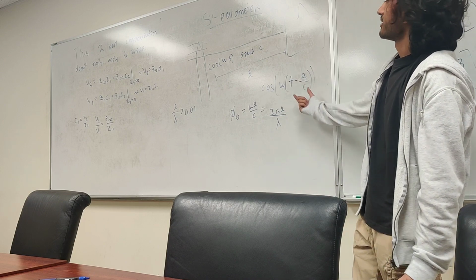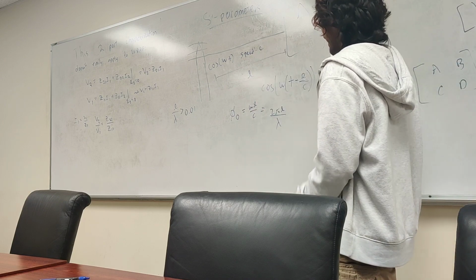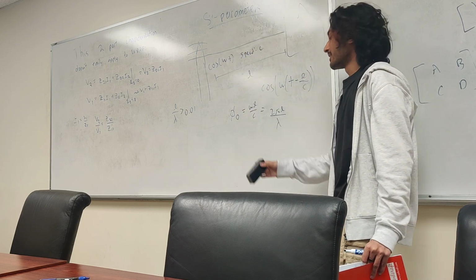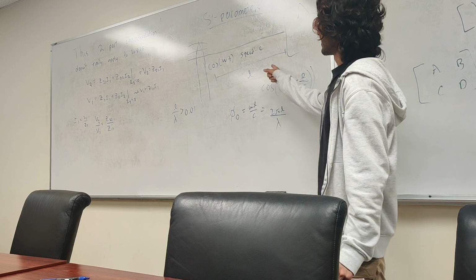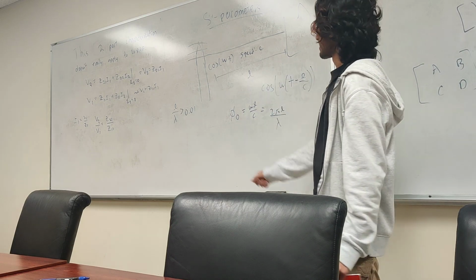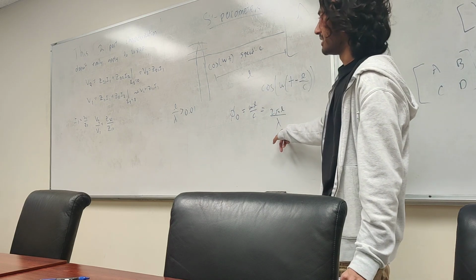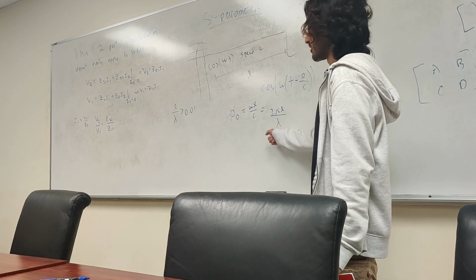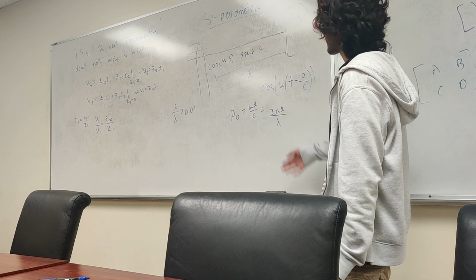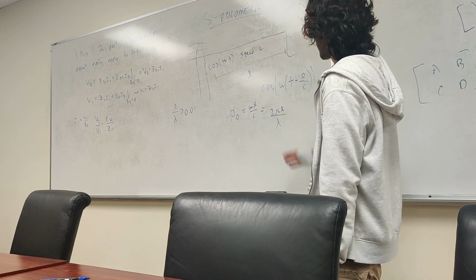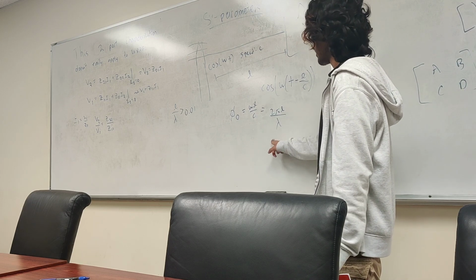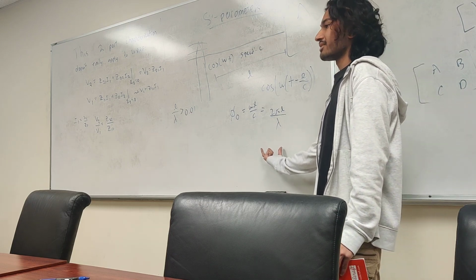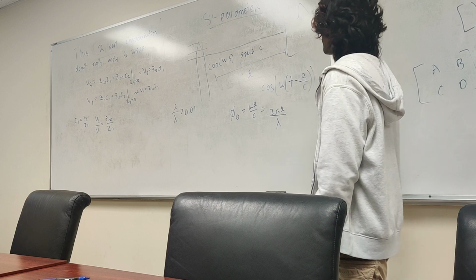If we shrink this down to the size of our PCBs, maybe half the size of this, our L becomes a lot smaller, which means the wavelength doesn't need to be as large to have an impact. So if we shrink everything down and go to higher frequencies for a smaller distance, it becomes more noticeable.